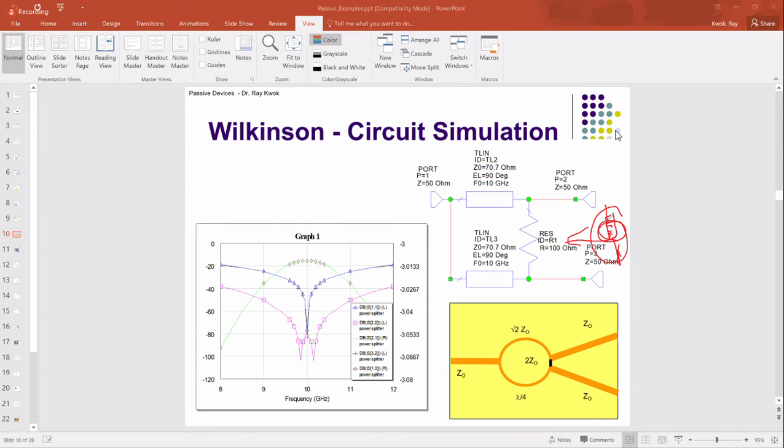These two lines are transmission lines with unknown characteristic impedance. So when you put that in here, you don't really know what you're putting here. You have a transmission line of unknown impedance, and then you have a chunk of resistor that doesn't work for high frequency. So that doesn't work. So people bend this and put a very, very tiny resistor. The size is about 40 mils length, that means 0.04 inches. Typically, that's how small it is.